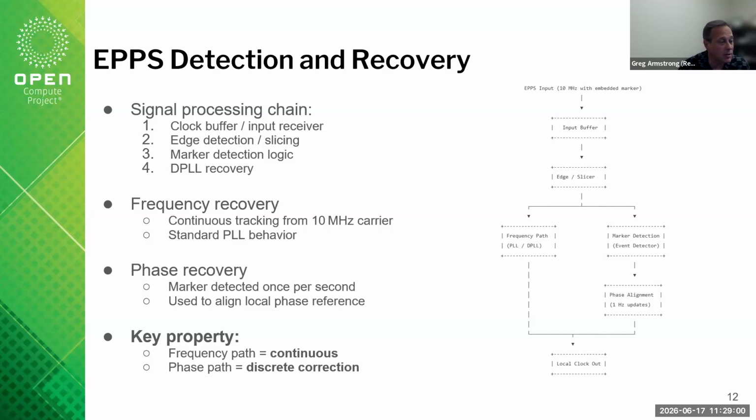So that marker could be used as a signal, or it could be used almost like a reset of the divider to make sure that divider happens at the exact same cycle, no matter what that clock is, a 1 over n or m over n relationship. As long as it has a 1 hertz common multiple, I can make sure it's aligned to that 1 hertz. But even if it's a half a hertz, then you can make a decision of picking an even cycle of 1 second or an odd, right, of that 1 second and still have an alignment relationship, even at a half hertz type interval.